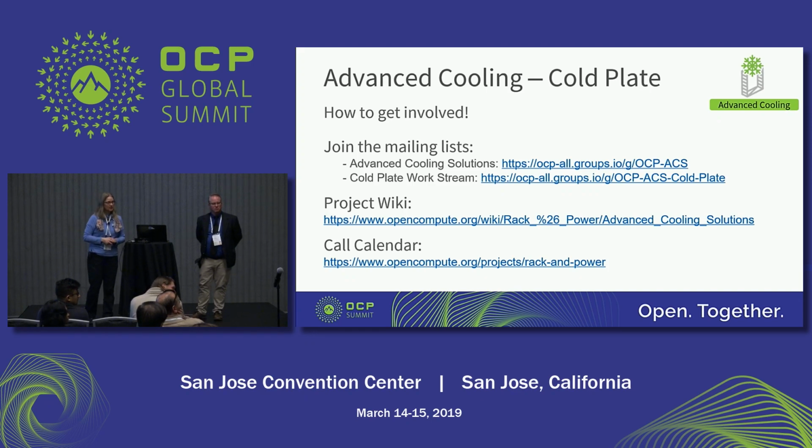Yes. I think I heard you say at the beginning that you're using 55 and 25 propylene glycol, but you were leaving it somewhat general so that you can use any propylene glycol. My comment is that different suppliers' propylene glycols all have different inhibitor packages and different biocides. So to put a wetted materials list out there, you have to call out the specific propylene glycol that you've used to do your analysis.